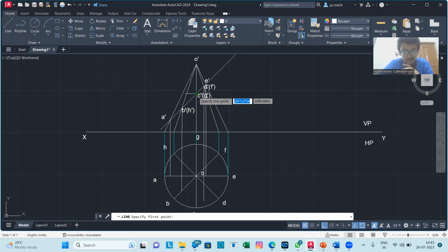You have to draw a line from here. You cannot project this line here. For example, you are having the section of OA. OA is here, the cutting plane is cutting here. So you are projecting this to OA. Similarly, you can project for OB and OH respectively. Whereas OG and OC is a straight line, so you cannot project this point directly. It will not intersect anywhere.